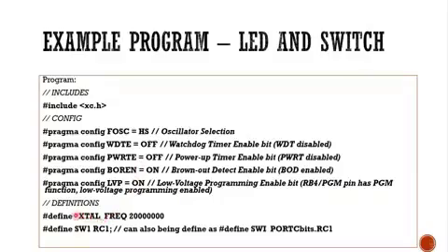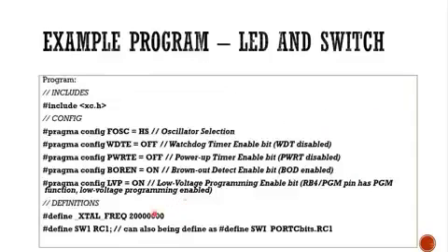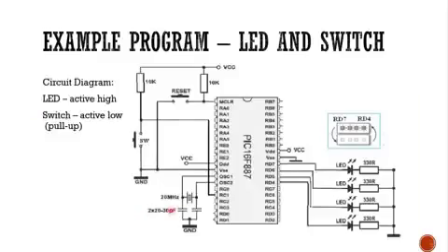And then the last one, this is the most important: the crystal frequency. Since you are using 20 megahertz, this one must be 20 megahertz. After this, this is the most important, you need to put it in every program. This only depends on the crystal oscillator.